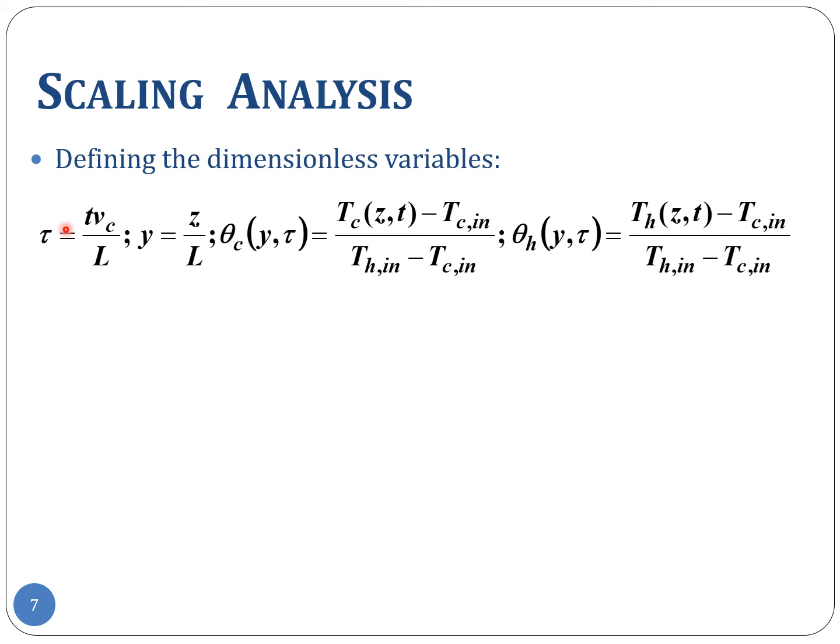What are the competing phenomena? Flow, axial flow along the z direction, and in the dimensionless coordinate system along the y direction, and the heat transfer from the hot fluid to the cold fluid, ideally in the radial direction, but we are not looking at a radial variation, and therefore the heat is just added uniformly at every cross section as we go along. Everywhere in the cross section, the same amount of heat is added.